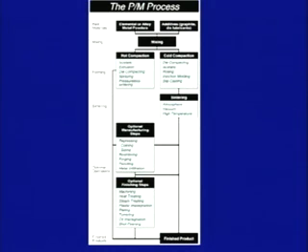Similarly, in cold compaction there are a number of processes, which can be die compacting, isostatic cold compaction, rolling, injection molding, slip casting. So basically in these first 3 steps we have seen that we make a powder of a metal, which is then mixed with certain additives, and this mixture is pressed under applied pressure, and there are different processes which are used to press this mixture. Now after that we sinter this product.